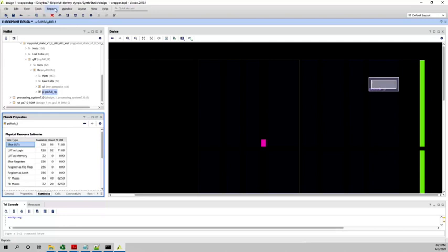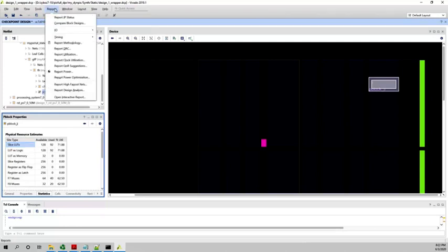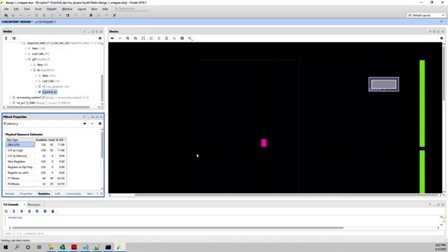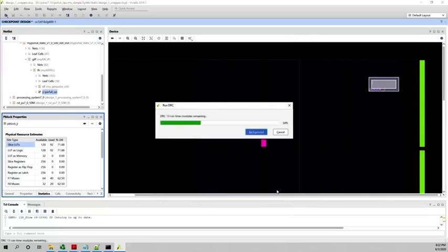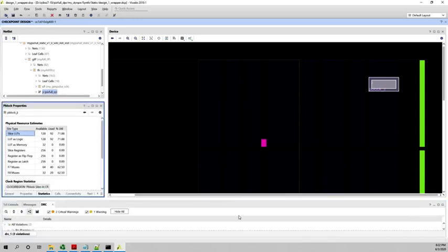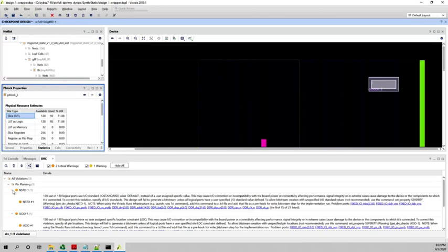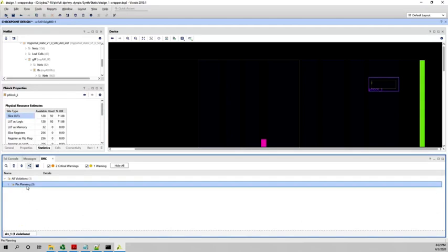So now what do we do? You are not done yet, by the way. It would be so easy if that was all you have to do. No. You have to actually run what we call a DRC, and check, remember, for the partial reconfiguration warnings, okay? If you get a bad warning, essentially it won't work at all, I guarantee you. Forget about the pin planning, by the way, it doesn't matter, because we have not yet loaded the PS IO constraints, so we don't need to worry about that. Oh, and apparently I was very lucky. I did not get any